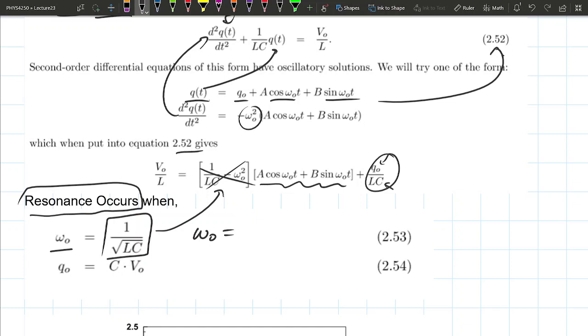You're just storing up bigger and bigger voltage. But in real life, the capacitor is not just a capacitor. It's a capacitor that has a little resistance on it. The wire has a little bit of resistance on it. The inductor has a little bit of resistance on it. So you end up losing that energy, and eventually you'll have a large voltage, but it's not going to be infinite. You're not going to be able to do fusion with it or anything like that.